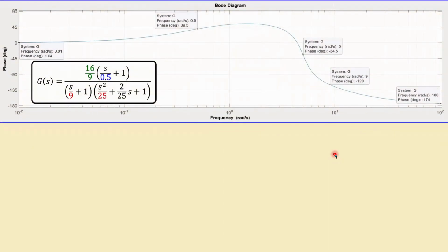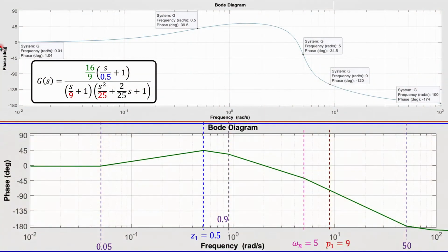Okay, now we also look at the Bode diagram for our phase. Again, it starts at 0, so it's close to 0. Of course, if you go to low frequency, this is very close to 0. It's just an approximation here for our case. And the first break frequency 0.5, we had calculated using asymptotic approximation. It was 45 degrees, but it is approximately here 40. So you can see again some difference.